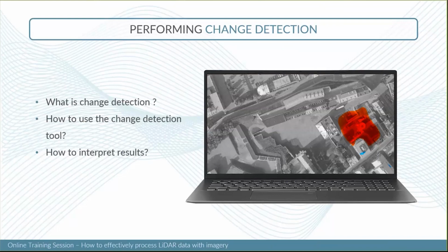You could use your reference DEM, and if you have different imagery data, use your reference DEM as your AT, and then compare the change between your photogrammetric processes.